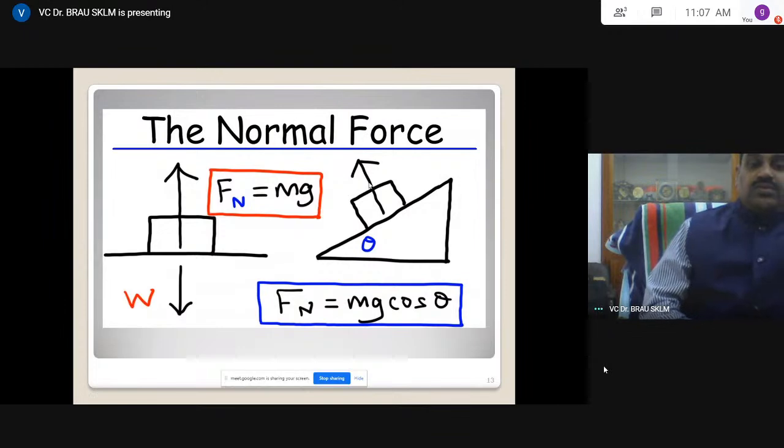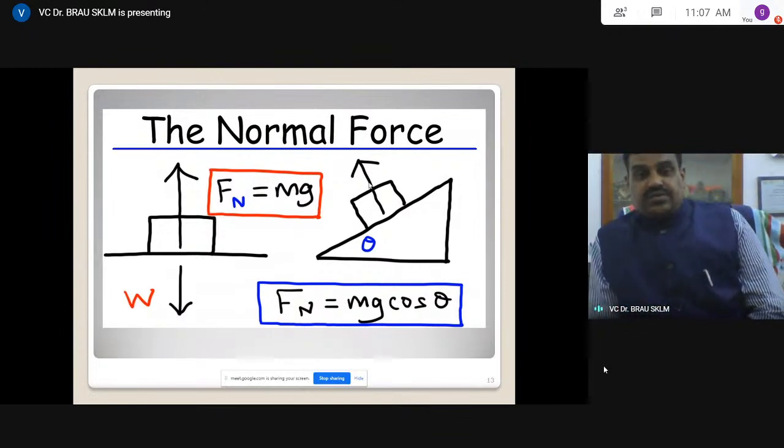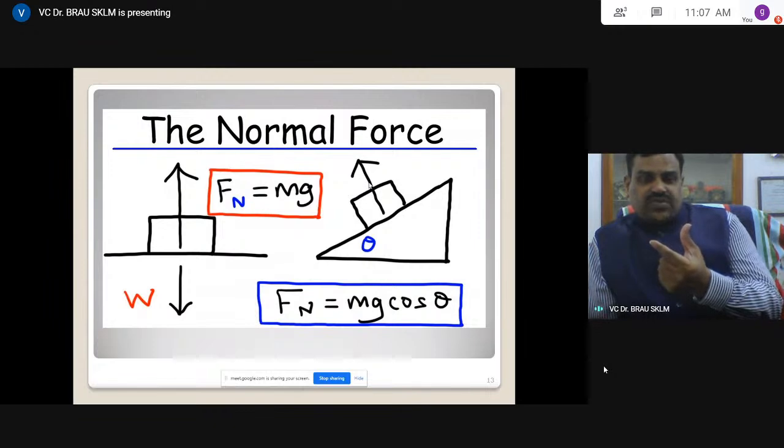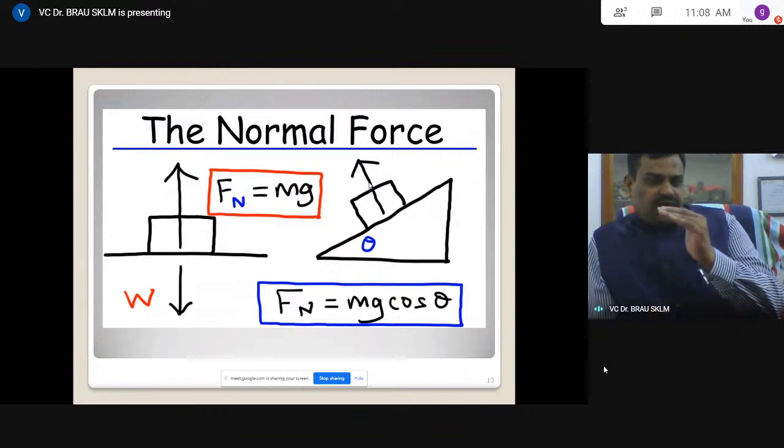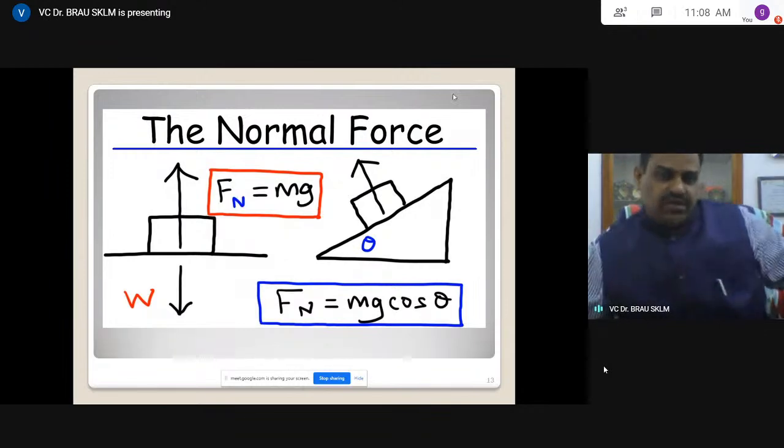So this is how generally we will represent it if there is a frictional force. For small angles of theta, the block is always at rest, in a static condition. If you increase the angle, then it starts sliding, and then the frictional force comes into the picture. If sliding, the frictional force is upwards, because W is downwards here. This is W cos theta and this is W sin theta. When it starts sliding downwards, the frictional force acts upwards.